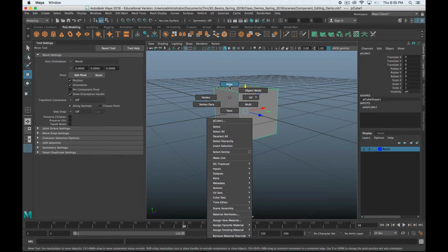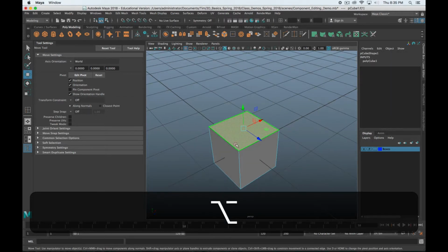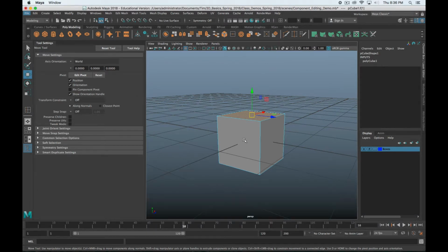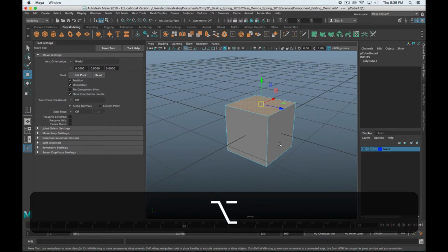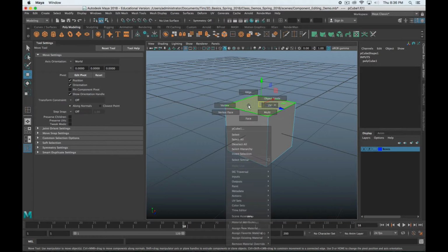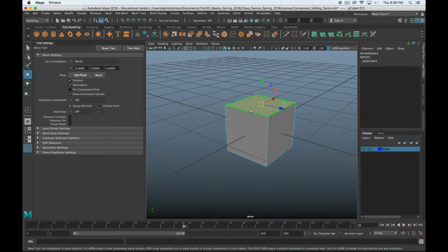Now let's talk about extruding, which extruding and edge loops are the two kind of tools I use the most to add geometry. And what extruding is, I'm always reminded of when I was little. I had a Play-Doh extruder, like different shapes you would put on the nozzle, and then you would force the Play-Doh through it, and then it would come out in the shape of a star or a circle or a square or whatever shape you put on it. It's kind of like what extruding is here in 3D. So if you select a face, you can also extrude edges, but primarily I extrude faces.